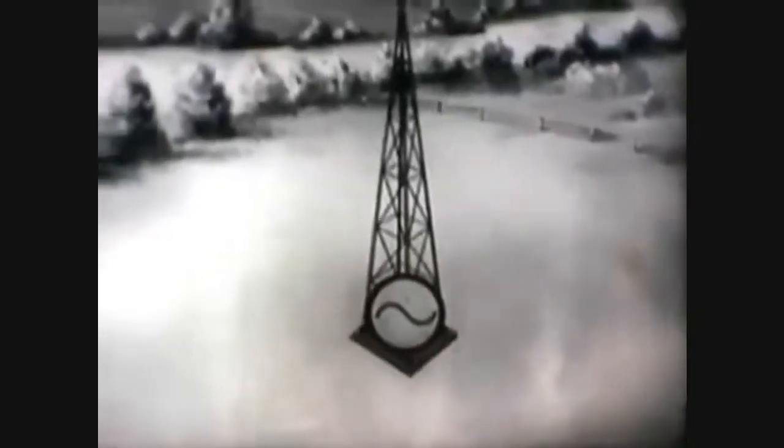Our upright conductor now functions as an antenna, a quarter-wave antenna. The quarter-wave transmission line with one conductor upright is quickly changed into a practical antenna system. The ground takes the place of the lower conductor. The upright conductor becomes an antenna tower. Our source of power becomes a transmitter, which is located some distance from the tower to prevent distortion of radiation patterns. The efficiency of a quarter-wave antenna depends largely on the nature of the ground.